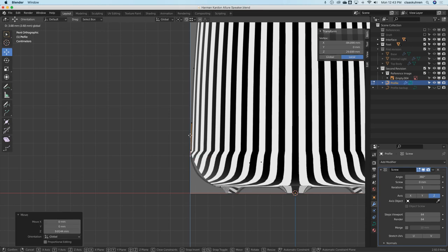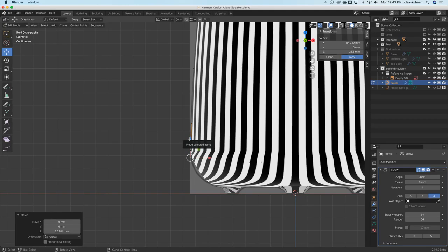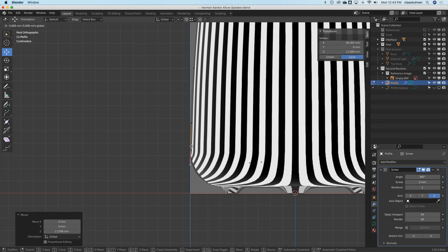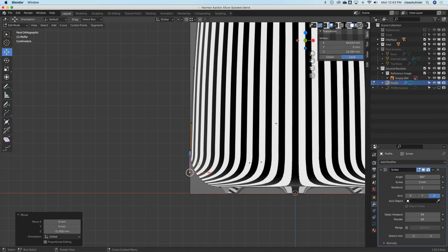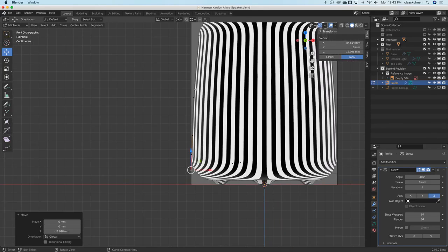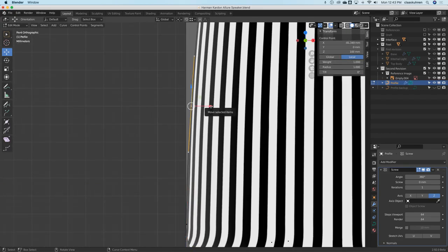So when we make this kind of short, there is a transition from this arc then to this arc, and you can really see how the zebra, where this point kind of is, starts to change its direction more abruptly. And when we push this one out, this is a nice flow. So this is kind of what they talk about as surface curvature.